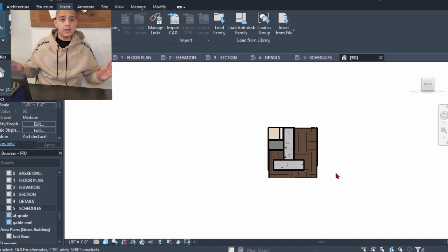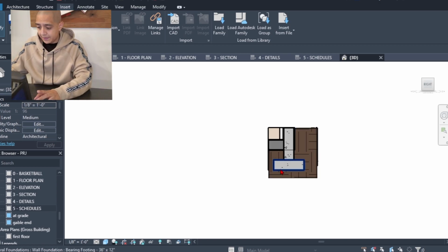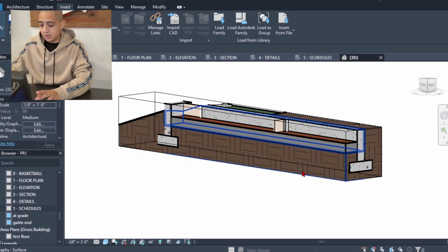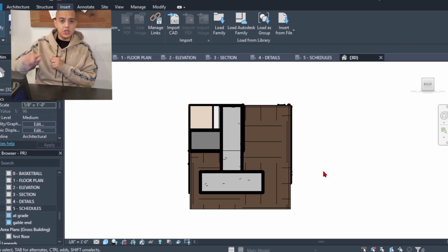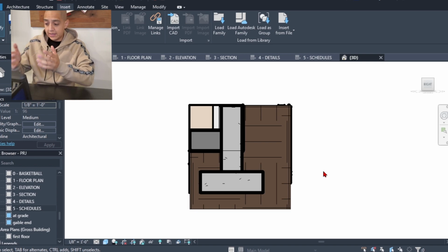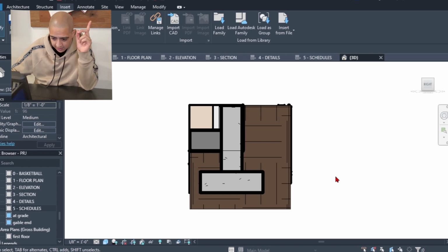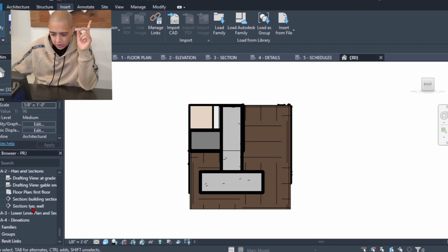It's not showing anything else of the house. You can see here in 3D view that it's that part of the foundation wall. And then you just cut it, zoom into it, and then you're just detailing out little pieces and parts that you see in this view. That's a detail view. And the last thing is schedules, which we'll just jump into an example.